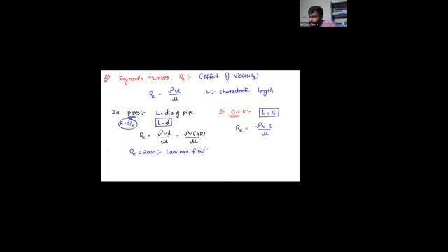See here, R, I can write this as 4 times rho V R by mu, Re naught. Yes or no? So whatever the Reynolds number in pipe is equal to 4 times the Reynolds number in the open channel flow, Re naught. Yes or no? Then what is the Reynolds number in the open channel flow? 1/4 of the Reynolds number in the pipe flow for laminar flow. 1/4.